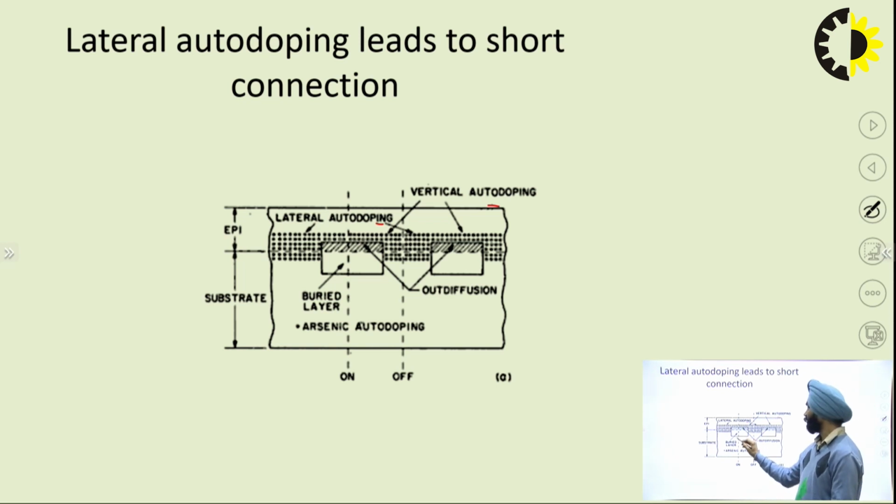So here we see that this is a buried layer that is created between the epitaxial layer, and due to the diffusion over this region, there is a buried layer that is created. There is a gas autodoping that is created. So we have to create a layer over here, which is the epitaxial layer, and there may be a substrate that is also doped by the arsenic layers.